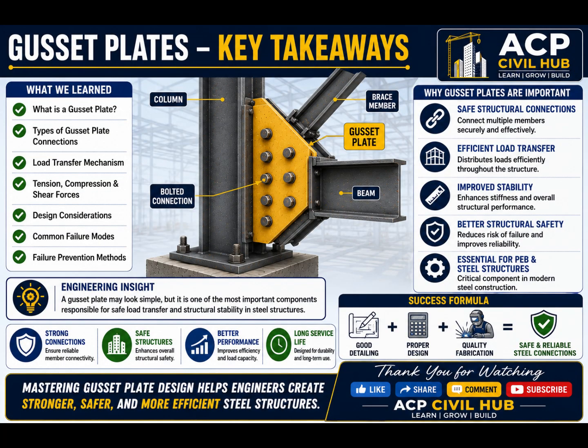Let's summarize what we learned today. We understood what a gusset plate is and why it is important in steel structures. We studied different types of gusset plate connections, including bolted, welded, and combined connections. We learned the load transfer mechanism from brace members to gusset plates, then to beams or columns, and finally to the foundation.